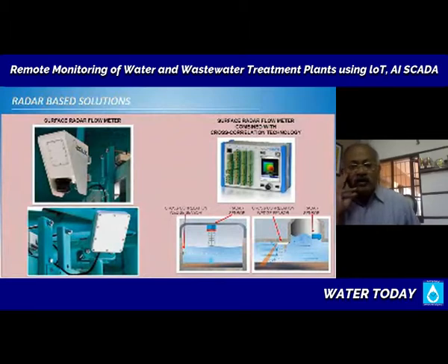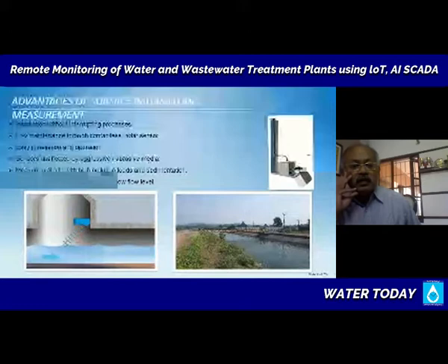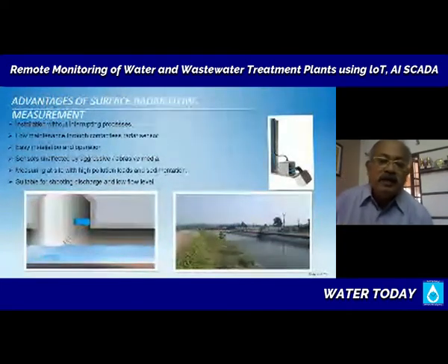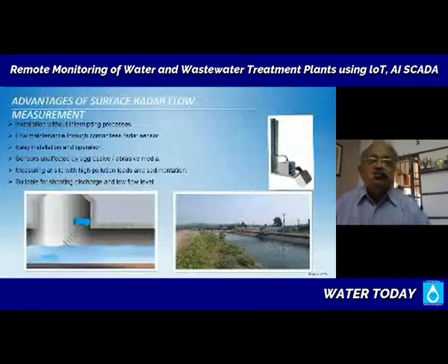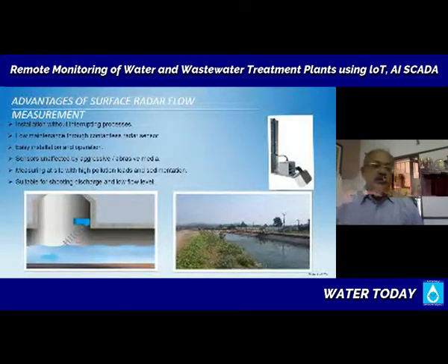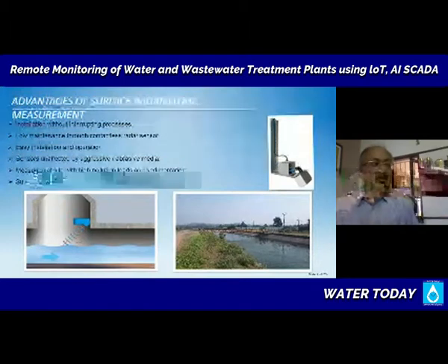So these are all the varieties of sensor technologies that are available for you for water. Now, what you are seeing there on the slide, there's a photograph of an irrigation canal on the right hand side. I'd like to point that out, and we have put our metering device right there on the bridge. You see a bridge there across the water. We install the velocity and the depth sensor from the bridge and calculate the volume of water that's going through the canal. So these are all very intricate, tricky ways of accounting for water.